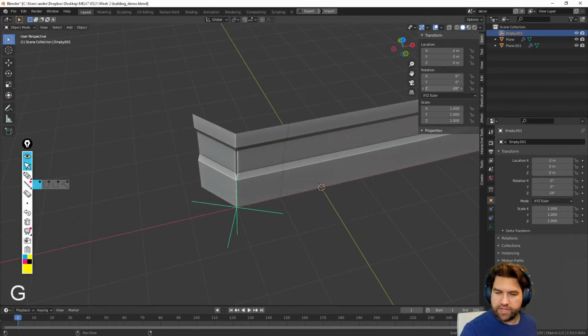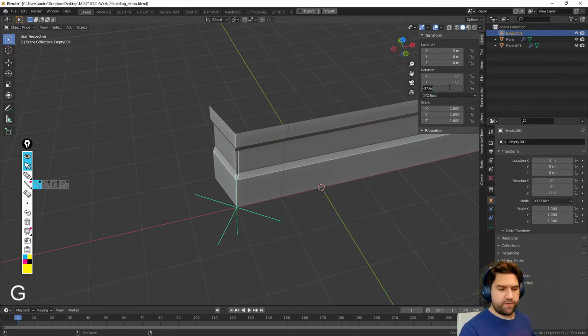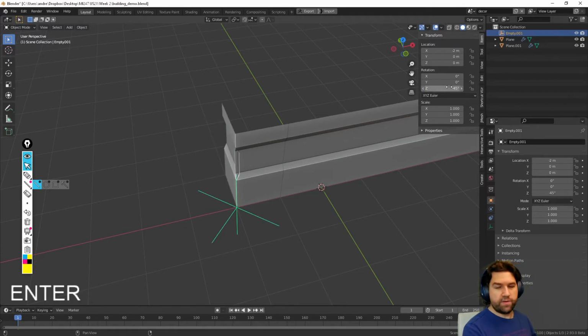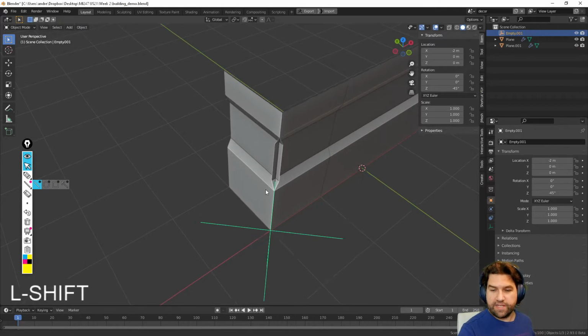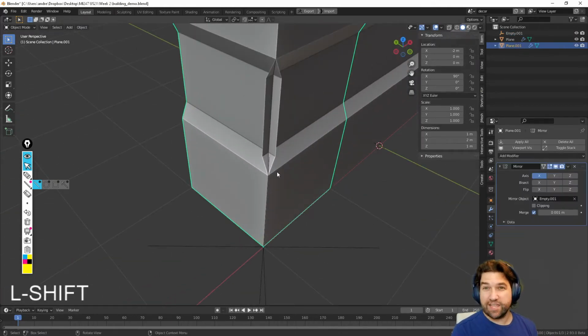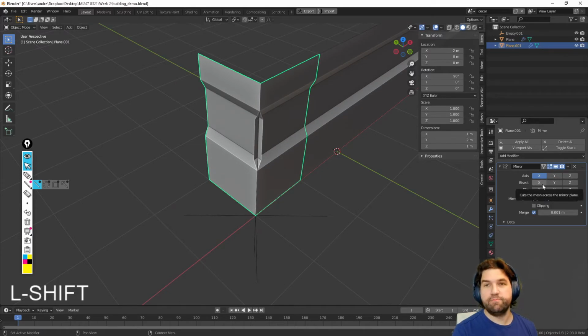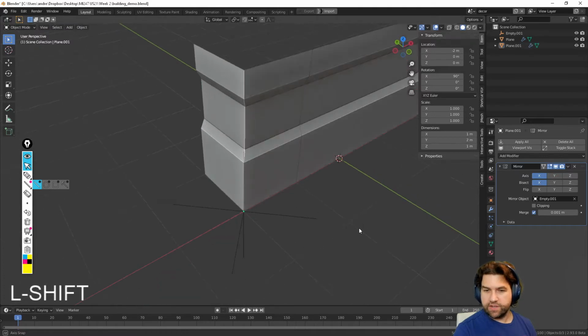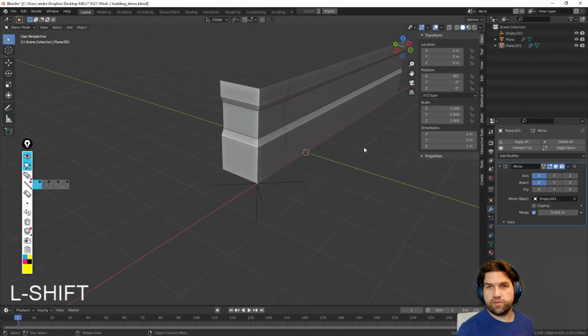It'll actually rotate this little corner piece. So if I set this to -45, that's rotating it enough to give me a 90-degree angle. I can get this corner wrapping around, but I still got leftover geometry. However, if I turn on bisect, it'll clip anything that goes across this. So that gives me a nice tight little corner.